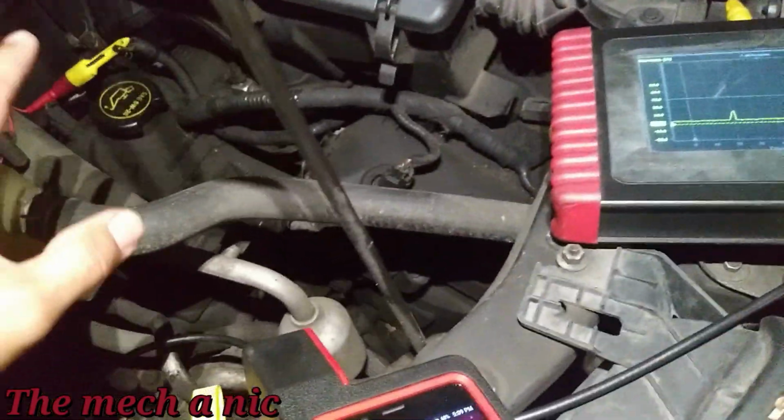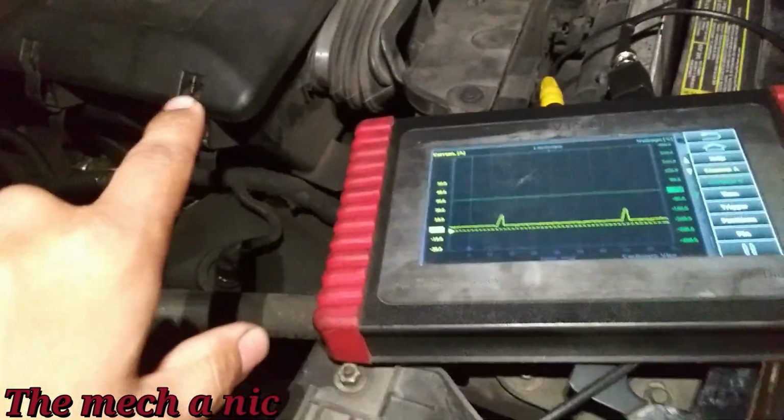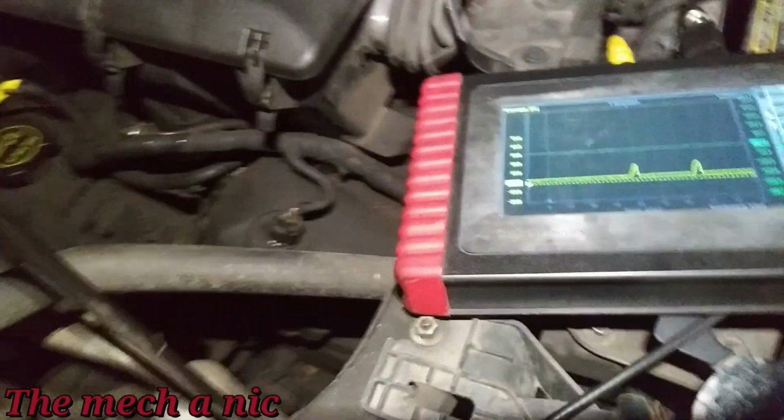I'm gonna let it run without touching anything. If this injector comes to life once it gets hot, it's a done deal. It needs a new fuel injector.